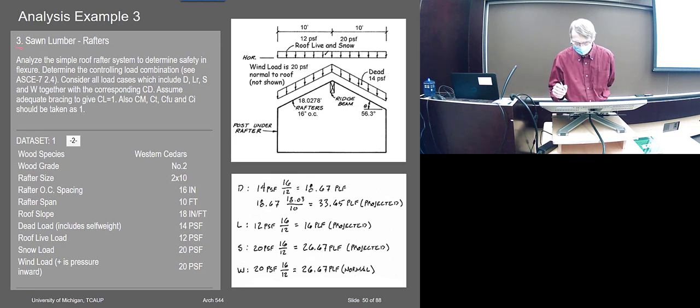And the main point that we'll look at with this example is calculating which load combination controls, how you determine controlling load combinations and still take into account the load duration factor, because you've got a different load duration factor for different combinations, and that affects the stress, so you've got to somehow account for that when you're choosing which combination controls.